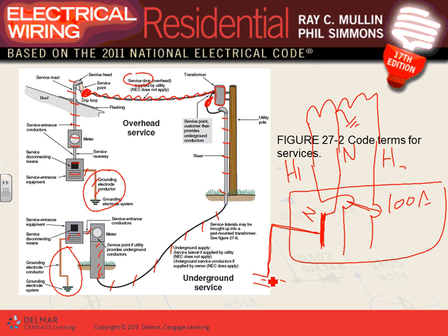You have to bond it and ground in the neutral. Any comments, any questions? Does it make sense? Yes, no? You're going to hear me, guys, all year talking about grounding and bonding. The first thing you do when you bring the power lines, here's my transformer coming from Xcel, right? Here's my transformer. We're bringing 3-wire in. You bring your neutral, you bond it to the ground. You bond the neutral to the grounding electrode system through a grounding electrode conductor.